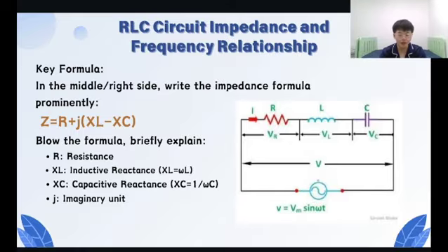To sum up, in AC circuits, even though the relationship between voltage and current involves complex numbers due to impedance, it remains linear. The impedance Z equals R plus jX allows us to consider both the resistance and the frequency-dependent reactance in a circuit. So, when we use more complex math, the fundamental relationship between voltage and current in AC circuits is still linear, just a bit more detailed, but by using impedance, we can fully describe and solve AC circuit problems.